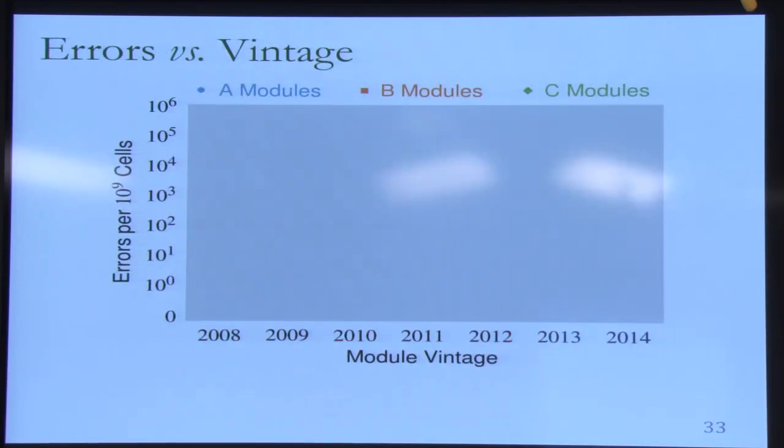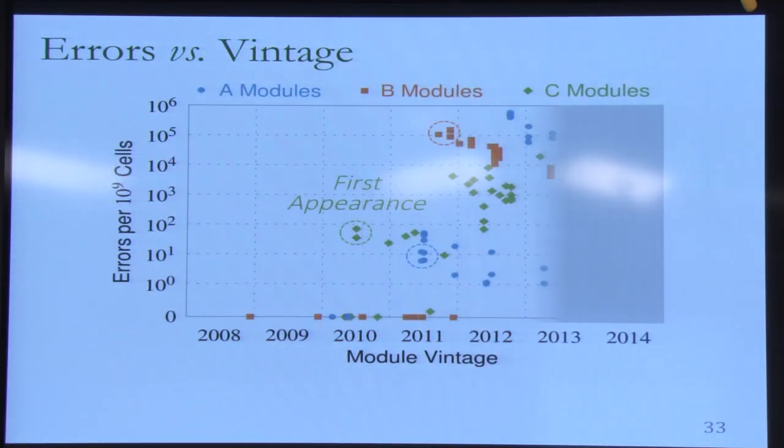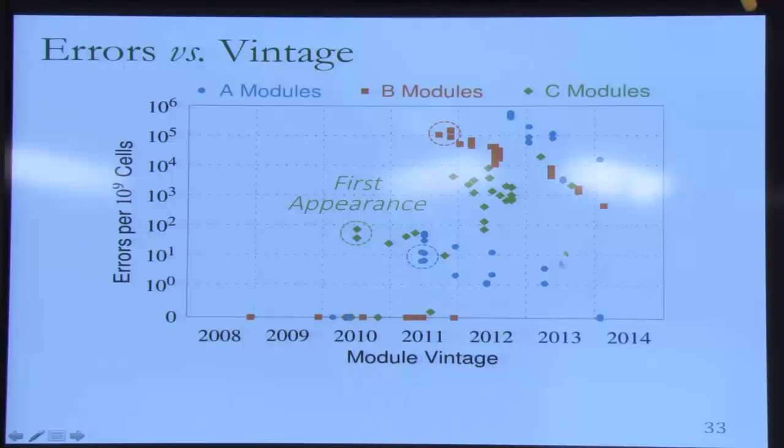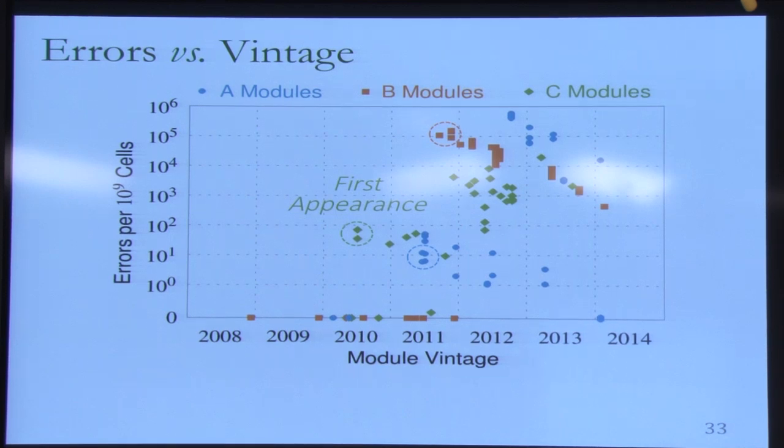And this is actually a real reliability issue, and it's been happening recently. So it wasn't observed until 2010, and it has happened in all of the chips that were tested that were manufactured between 2012 and 2013. Well, why is it happening? Because this is really a scaling issue. As you reduce the size of the cells, they become more vulnerable to disturbance, right? It wasn't happening before because it was easier for the DRAM manufacturers to contain this kind of errors. They could test for it. Maybe they didn't even need to test for it because this disturbance was not as big of a deal, right?